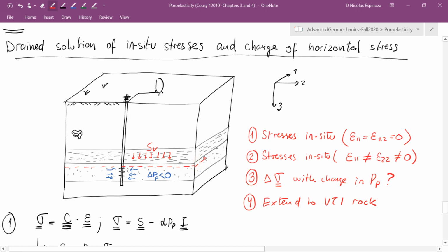In this particular example, we're assuming that the entire reservoir, or at least this entire block, has suffered the same change of pore pressure. And that's relatively a good assumption when you have a very permeable formation. All right, and as a result of the pore pressure change, I'm going to have this compaction, and whatever was, for example, over here before is going to compact into a new volume and is going to have a change of length which is proportional to that compaction.